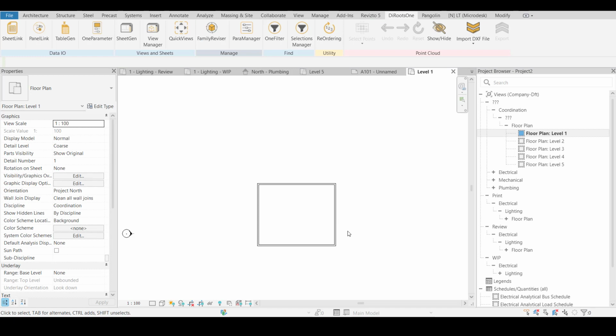So normally when we put in a scale, we also need a readable drawing, so we cannot have any scale of our choice. Let's say we are setting a 1:100 scale at A0 paper size, and in that case our portion of the building on the drawing covers only this much. So in that case we have to have a part plan. Part plan means even for the same ground floor you will have 2 or 3 drawings according to the size of your building. We are not going to compromise on the scale, and we are not going to print as fit to paper. We are going to print in actual scale, so that when they measure with a physical scale on the paper, they will find the exact distance.